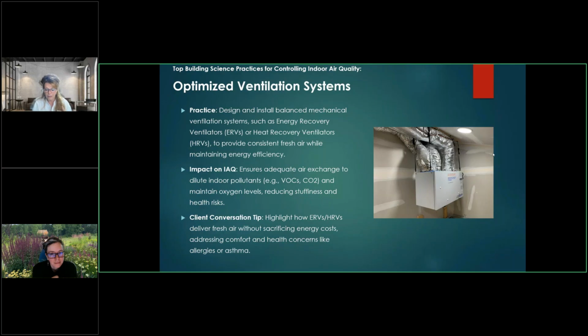Now, a ventilating dehumidifier is supply only, and that's typically because houses are a lot of times under exhaust. And if it's not a high-level, passive house kind of construction, you typically are going to be a little bit more negative. So we can do that supply positive pressure. If a homeowner can't afford both, I would typically recommend in a mixed humid to a humid climate to always go with the ventilating dehumidifier. You don't have to use the ventilation.